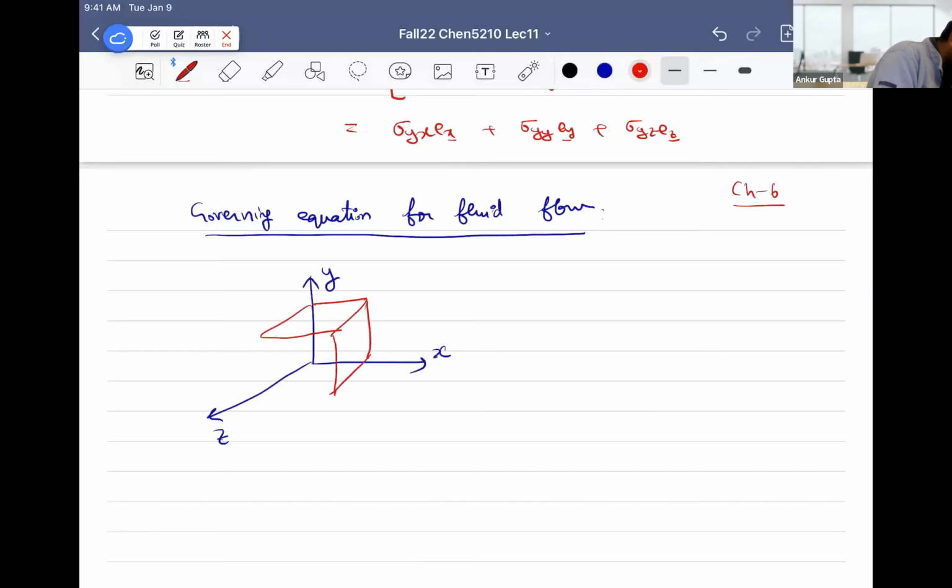So, all right, we'll go back to the control volume. So again, we saw the stress tensor and the stress vector, and now we're thinking about a force balance for fluid flow on a control volume. Remember, this is very similar to what we did in part 1, delta x, delta y, delta z. And as you saw in one of the exam problems, we gave you in minus out plus generated is equal to accumulated. That was the idea of the steady state and so on. That was for a conservation of heat, right? A scalar has the value of in minus out plus generated is equal to accumulated.